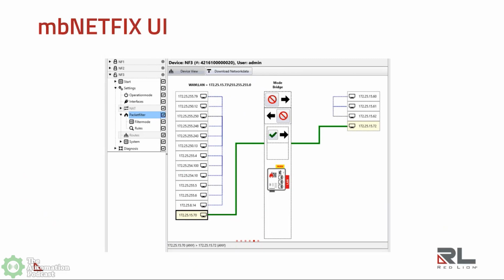If that input goes off, we block. Oh, that's awesome. Yep. That's definitely something like you put on the HMI or you put a key switch on the front of the panel and you only allow remote access when somebody on the plant floor says you get that access.